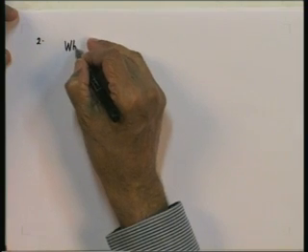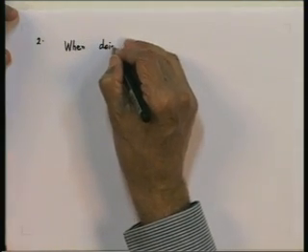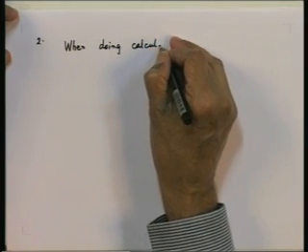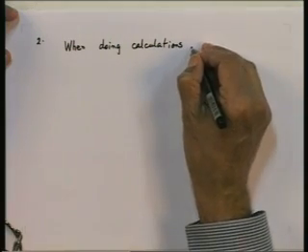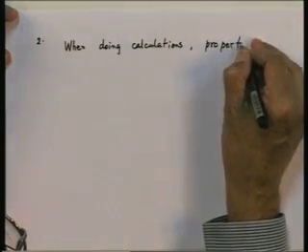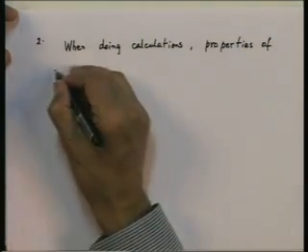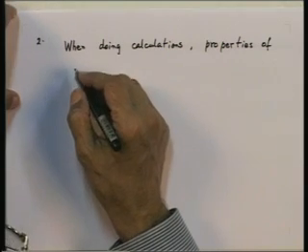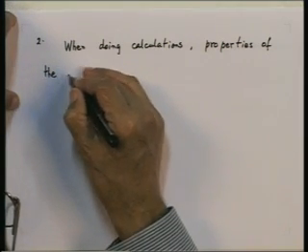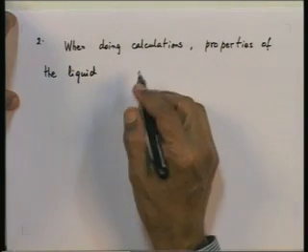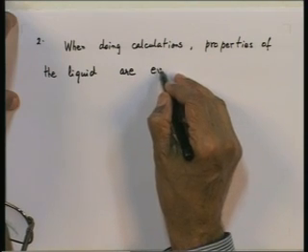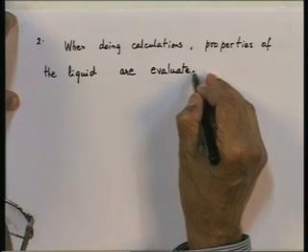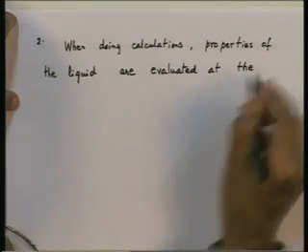The next comment which we want to make on the Nusselt result is, when doing calculations with it, properties of the liquid are to be evaluated at the mean film temperature.